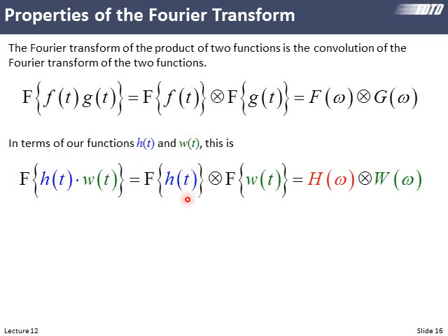This is the actual physical frequency response of the device. But we're convolving it by the Fourier transform of the window. Our window is a square function, so this comes out looking like some kind of sinc function. We are convolving the actual physical spectrum of the device with a sinc function, so it's being blurred. The actual spectrum that the physical device would have is being blurred by this sinc function. So clearly we want that sinc function to go to 0 in duration, but that requires this window goes out to infinity, which is not physical reality.